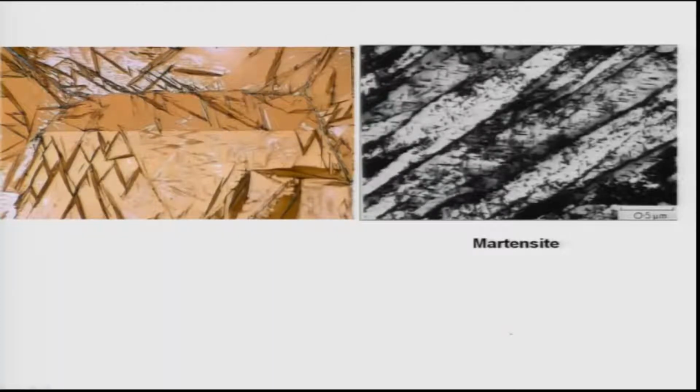Now, most of these martensitic plates start from one of the grains of austenite and in many cases extend to the other grain boundary. So, that means they are pretty long and they have the shape of a lens, just like this, and because they are lenticular shaped and have finite thickness, they are termed as laths or plates.